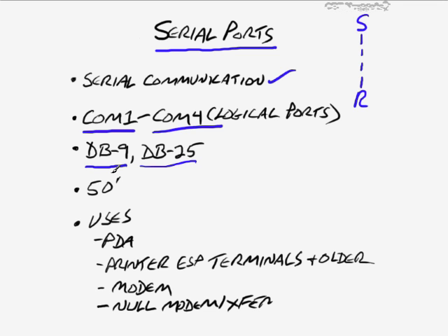Also, by the way, depending upon the manufacturer, there is such a thing as a standard serial cable where the pinouts are industry standard, but very often you'll find specially made serial cables made specifically for different devices, where maybe some of the unused pins on the DB25 are designated for a special purpose by a manufacturer, or maybe a couple of pins are crossed over for different reasons. Now, I'm not going to spend a whole lot more time on serial ports, only because they've largely been replaced by other things, such as wireless technology like Bluetooth, or faster connections such as USB or FireWire.